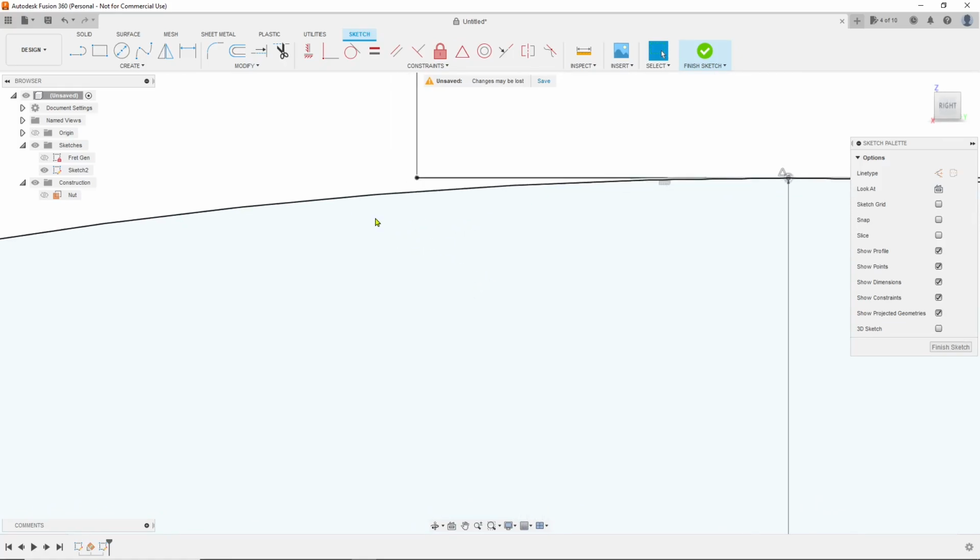Now I'm going to go up here. Now I want the sides of this fretboard, both here at the nut and back towards the heel, to be a 1/4 inch thick on the sides, even all the way down the side of a 1/4 inch. That way the scallops will all look even, and also that leaves a little extra room under the scallops to put in normal sized fret markers. It does make a little bit thicker fretboard that you have to compensate for somewhere.